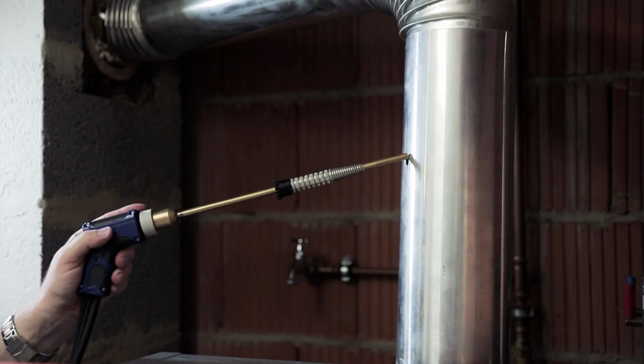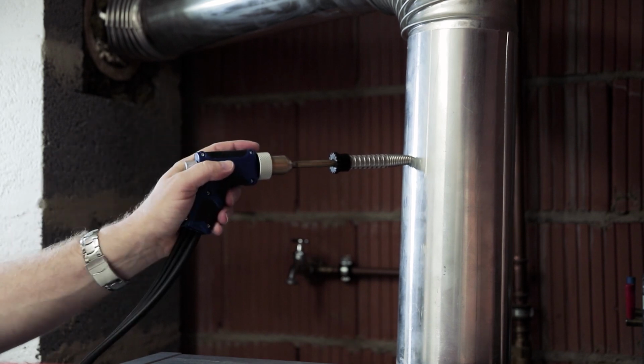The gas appliance has now been running for a few minutes. The Wöhler A 450 has adjusted itself to the room, in other words, calibrated to 20% oxygen by volume, and now I can insert the probe and start measuring.